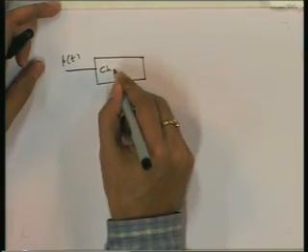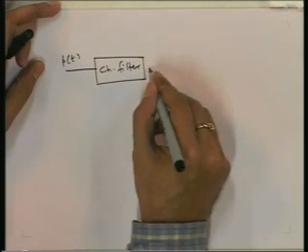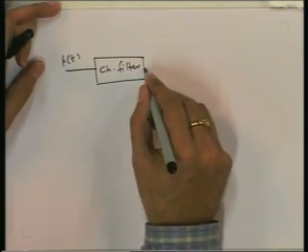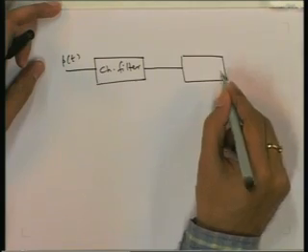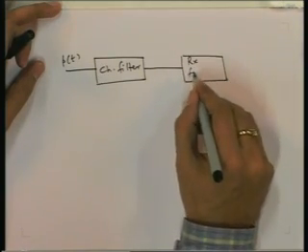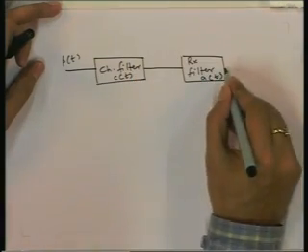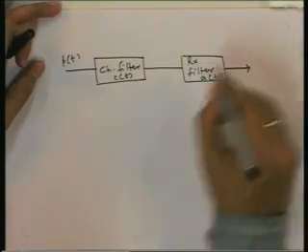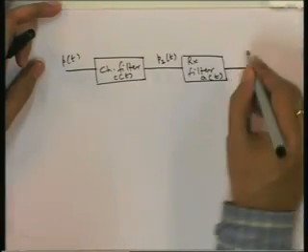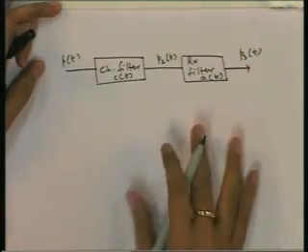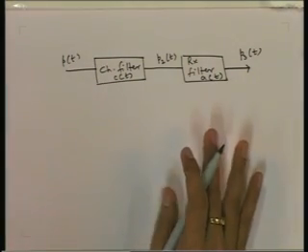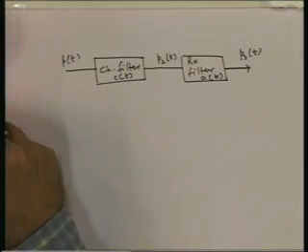This is the channel filter. We are not considering the noise which would have come here after the channel filter, and then it goes through the receive filter. This is c(t), this is a(t). So we call this p2(t) and this as p3(t). Now we have also discussed the condition to have 0 ISI. What is the condition on p3 to have 0 ISI? That was given by the Nyquist criterion.